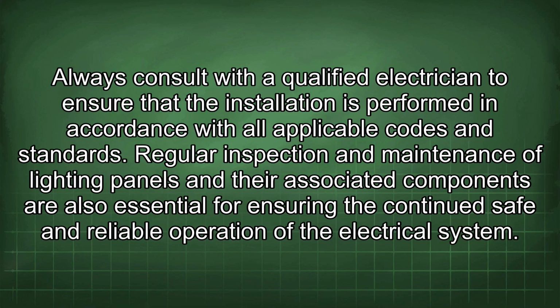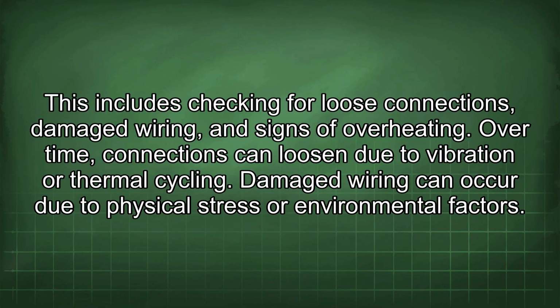Always consult with a qualified electrician to ensure that the installation is performed in accordance with all applicable codes and standards. Regular inspection and maintenance of lighting panels and their associated components are also essential for ensuring the continued safe and reliable operation of the electrical system. This includes checking for loose connections, damaged wiring, and signs of overheating.